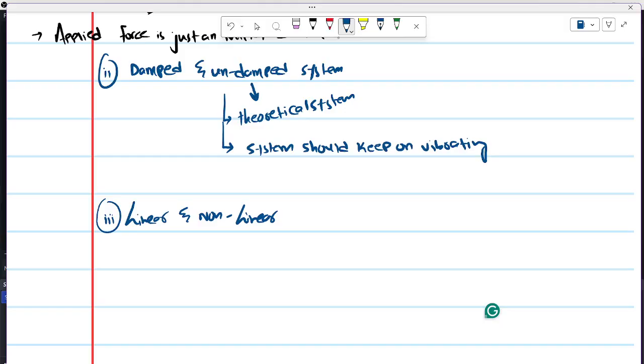So let's say spring, we know that F equals kx. For every 1 Newton force, the spring should, let's say, extend 1 centimeter or 1 meter. For a second Newton of force, the spring should extend by 2 meters and so on. But if your spring is behaving differently, it is clearly a non-linear behavior.